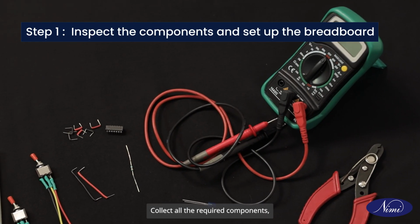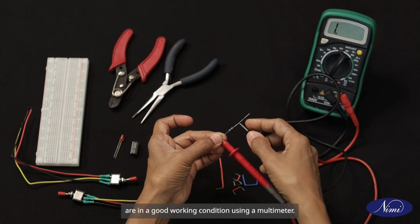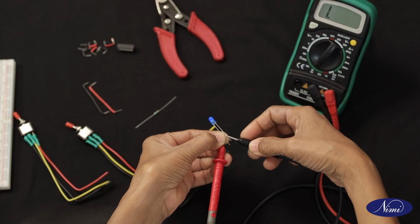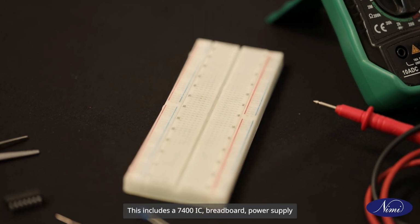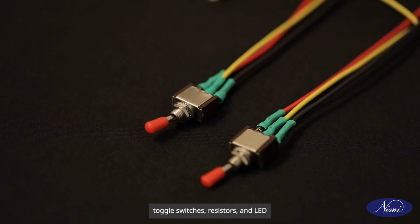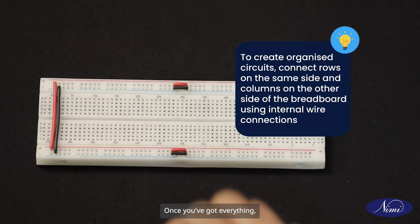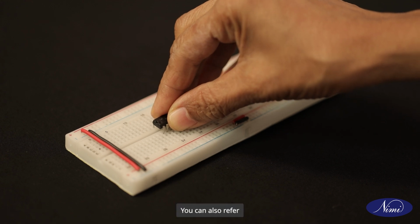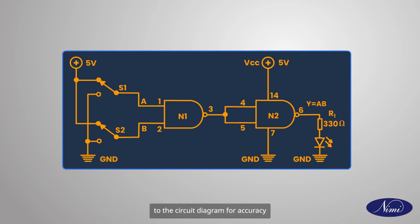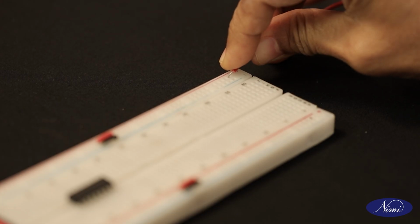Collect all the required components. Check them. Ensure the resistor and LED are in a working condition using a multimeter. This includes a 7400 IC, breadboard, power supply, toggle switches, resistors, and LED. Once you've got everything, mount the 14-pin IC firmly on the breadboard. You can also refer to the circuit diagram for accuracy. Connect linking wires from the power supply to the breadboard.